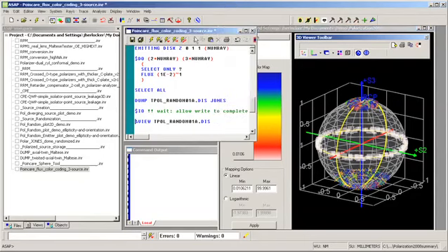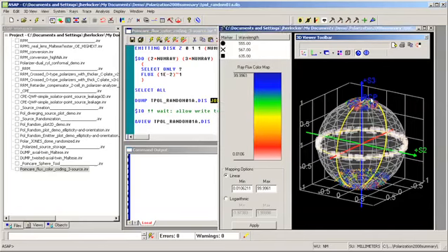The way we open a ray set in the Poincare Sphere Visualization Tool is first to dump that ray set using the Jones vector format for polarization, and then use &view to read the file into the 3D viewer. So this is the 3D viewer running the Poincare Sphere Visualization Tool. There are a few things worth noticing about this.